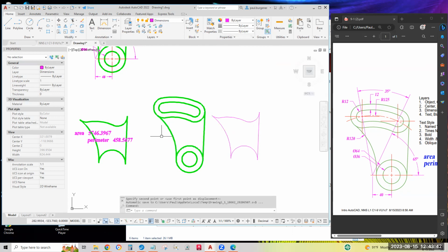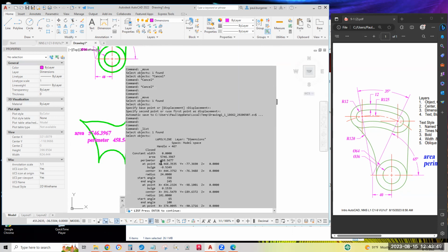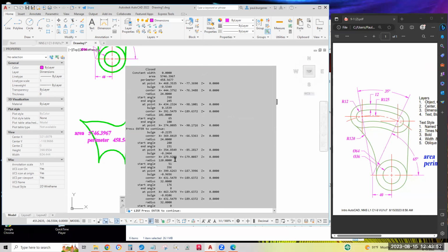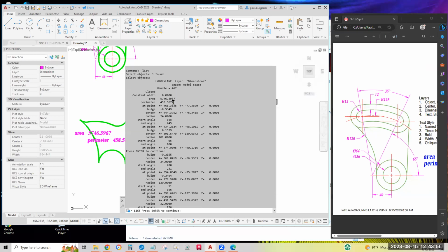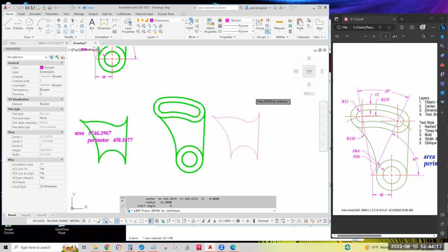We'll do the list and copy paste again into MText. List, select, enter. And there's the area again. I try to select those 2 lines and it thinks it's hitting enter. So scroll back up, or selected that much. Control C will copy to clipboard, or right click and pick copy. Click in open space and it shoots back down to the 3 visible lines I recommend.